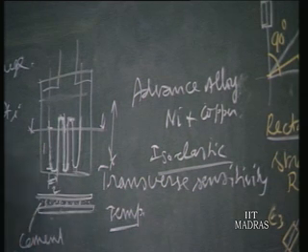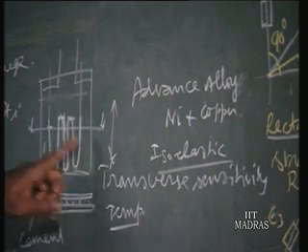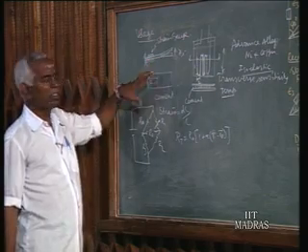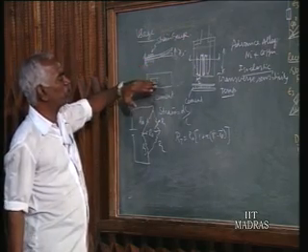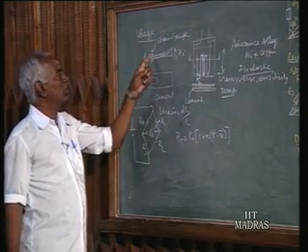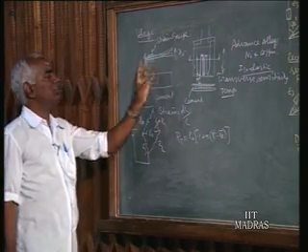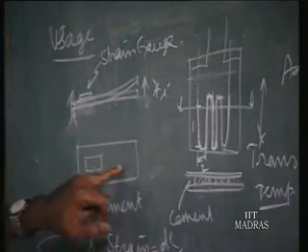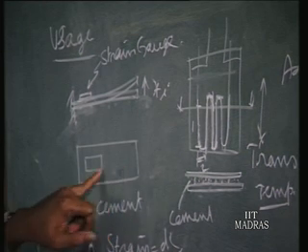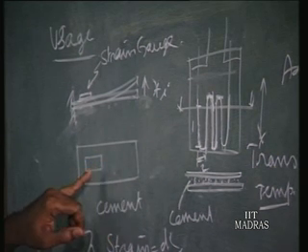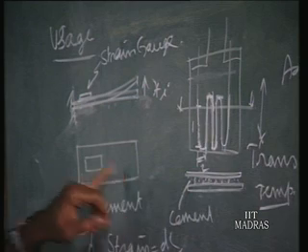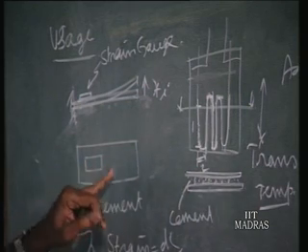But suppose we fix this strain gauge over mild steel or some other material, you will find the coefficients of linear expansion are different for the strain gauge wire and the base material. Then there is a difference in expansion of the wire and the base material. Suppose the base material where it is fixed expands more than the strain gauge wire, then for any given temperature rise, the wire will be pulled by the base material.